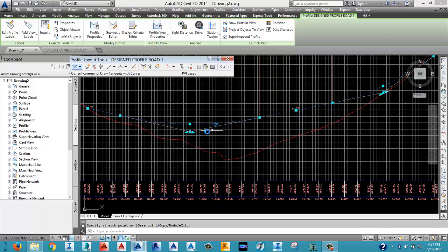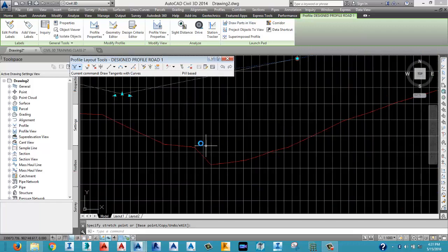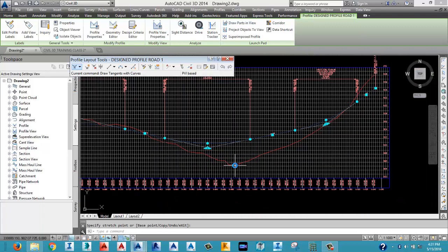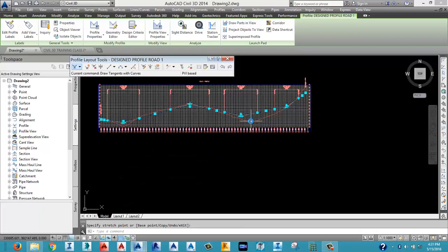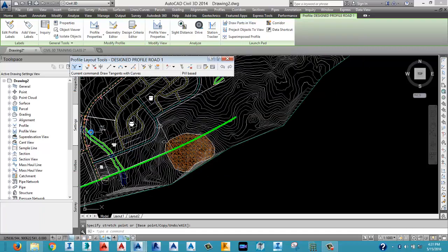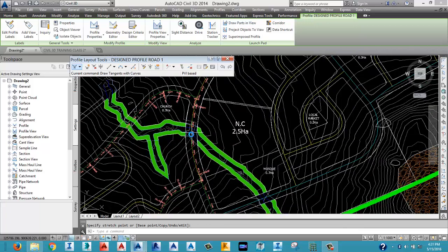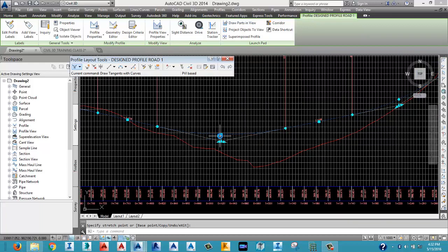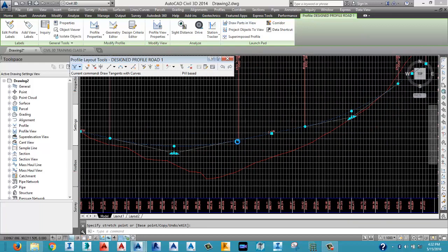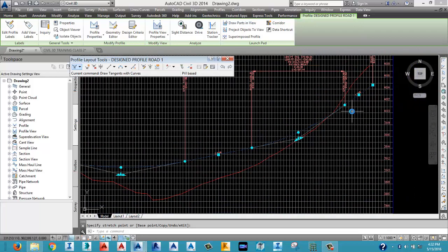This is a possible bridge location. Bridge? Yes, this depression. From what you have in your plan, this point is just here. So there's every tendency there's a bridge here. So the grade must be raised to give way for the location of the bridge around there. So the grade is always higher up around there. You backfill.